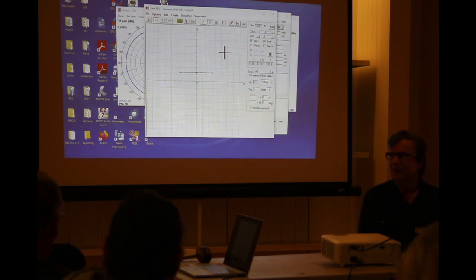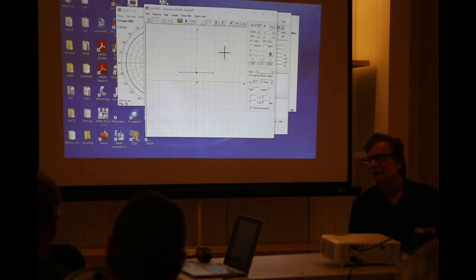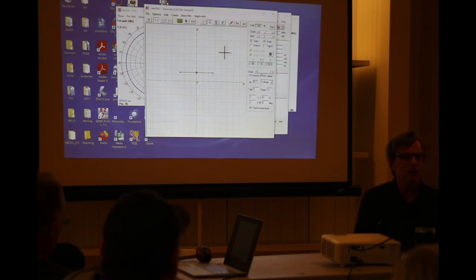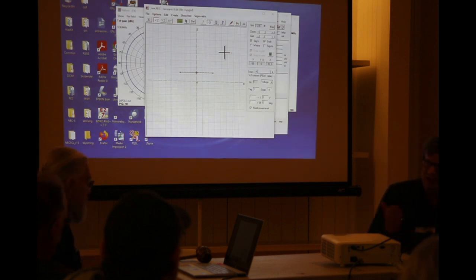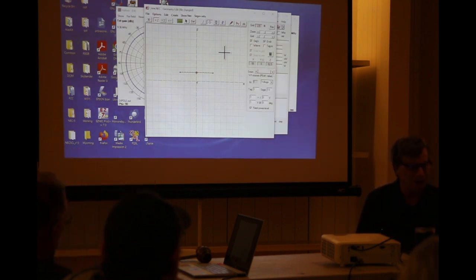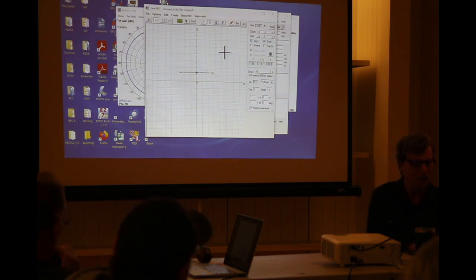Now, I know you didn't want to get into it, but can you give us a summary of why? Basically because when you have a phased array, you have interaction between the antennas. You have mutual coupling, and that can change the impedance and the current phase dramatically. Whereas with voltage, we just assume that the antenna is going to have the voltage, whatever we're putting in there. But anyway, we're going to start with a voltage source here.